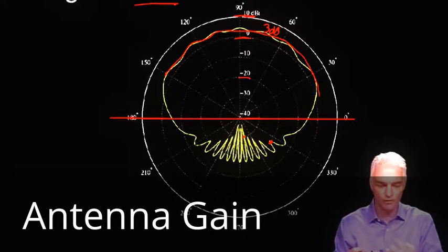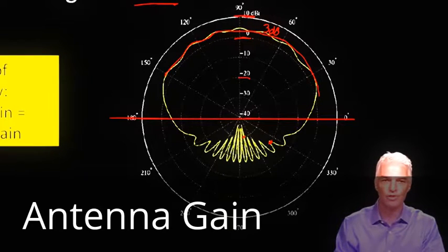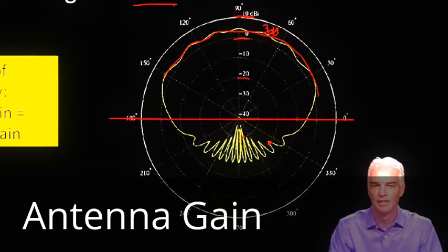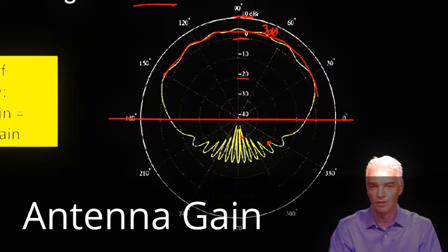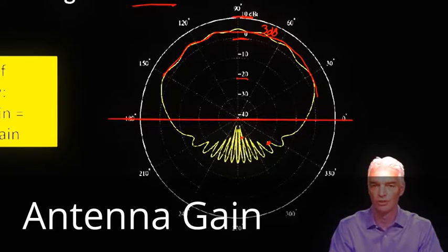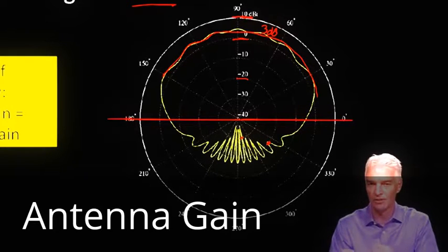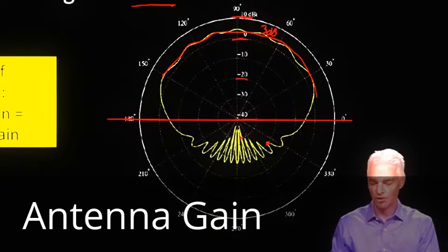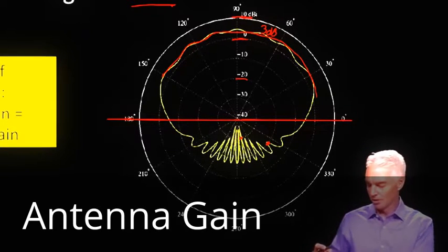How would it receive a signal? Well, that's where we make use of this nice principle called the principle of reciprocity that says receive gain is equal to transmit gain. We don't have to get into the details of why that is true. You just need to know that it is true, and you can think about an antenna in terms of how it would transmit, and then you can understand how it will receive. So that's what a patch antenna looks like.